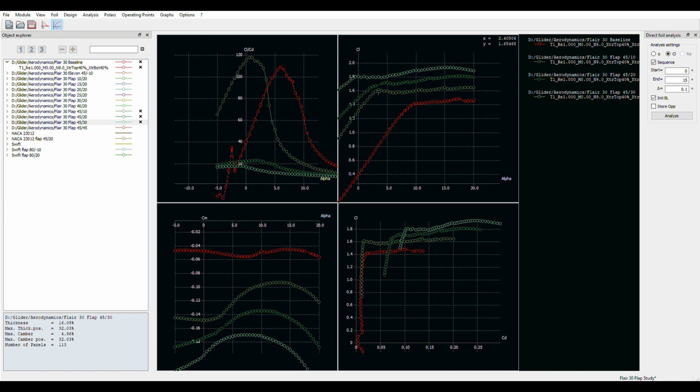He tries to counteract these by pulling full up elevator, which then dumps what remaining lift he has out on the wingtips down to essentially 0. So he dumps the flap, pulls in elevator, and loses all the lift that's on the wing. All of it just goes to nothing because he's totally stalled. The entire wing is not flying. And that's when you go to sudden nose down, vertical, straight into the ground.